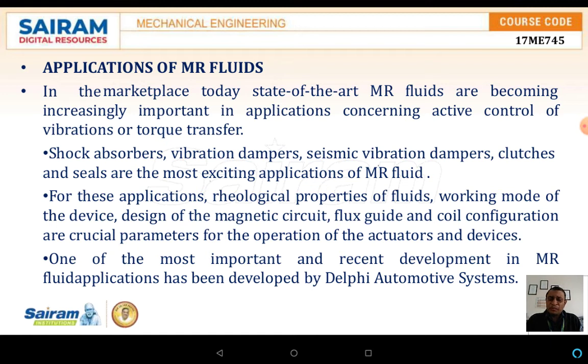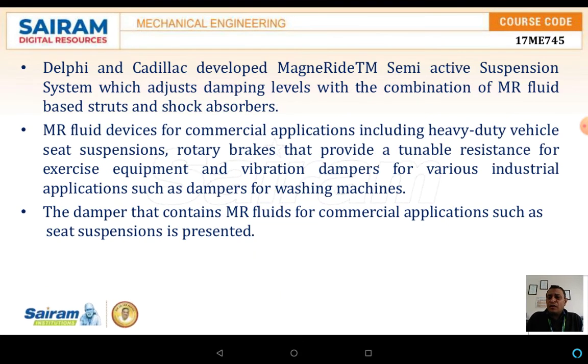One of the most important and recent developments in MR fluid applications has been developed by Delphi Automotive Systems. Delphi and Cadillac developed a semi-active suspension system which adjusts the damping level with the combination of the MR fluids based on the status of the shock absorbers.